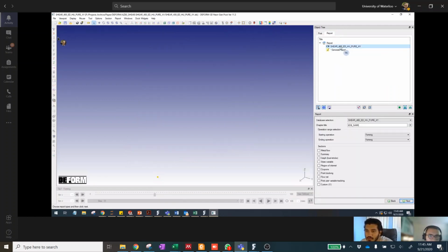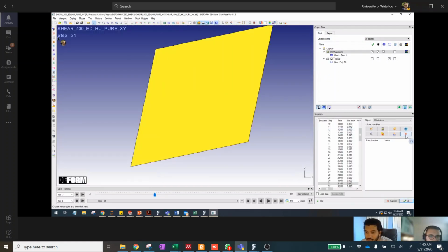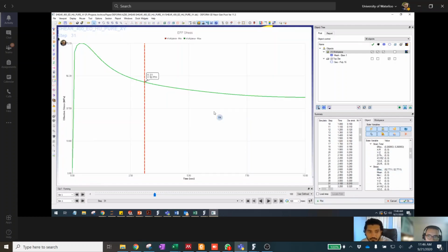Just do the effective stress then. Effective stress, I have that information right here, just to see how it's varying. Okay, so this is good, now it's flat. Perfect, that fixed that. It's not increasing, it's flattening. I think it matches very closely to the material curve.